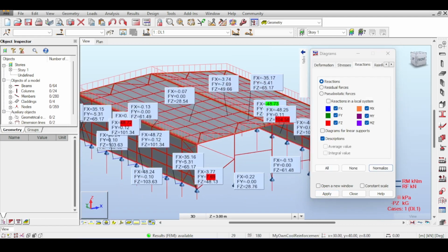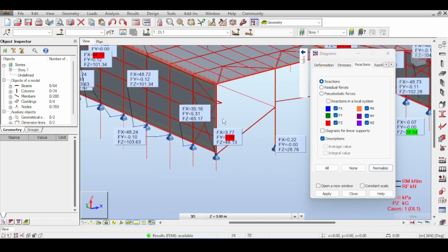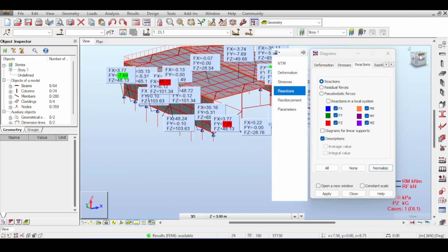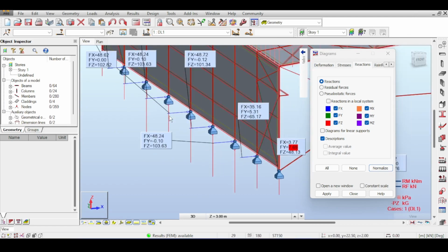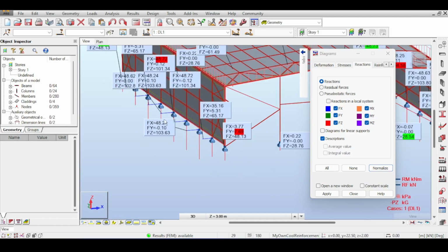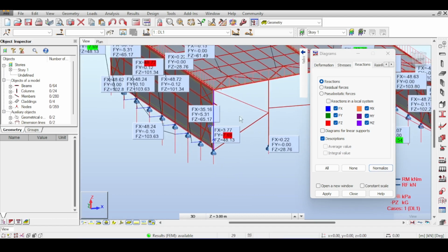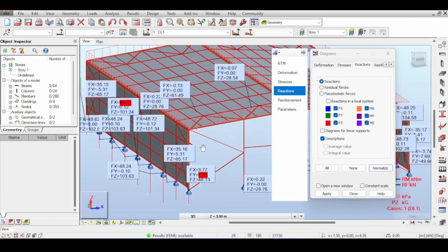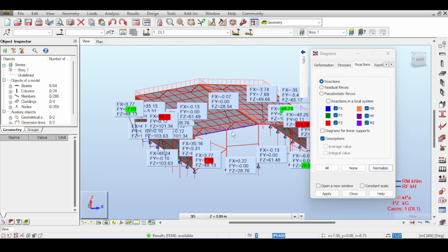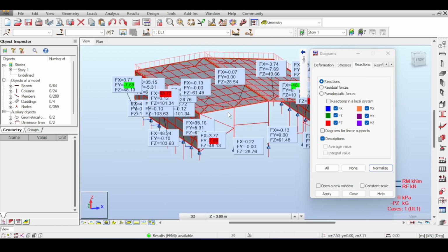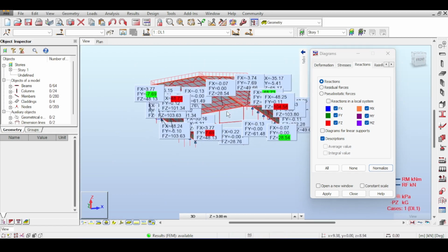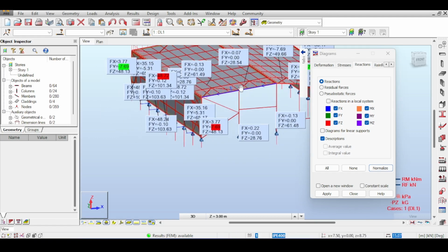Why do I want the reactions? Because I want to talk about something called accidental loads. Accidental loads, as we have explained in 2 videos, I'm going to link them in top right, are basically loads that are applied to account for accidental eccentricities, and this equivalent horizontal force you try to do is here to account for any global imperfections in the elements. So I've explained this and calculated this in videos before. For this specific portal frame, it's 0.3%.